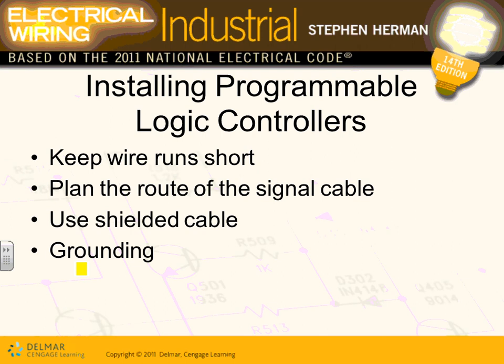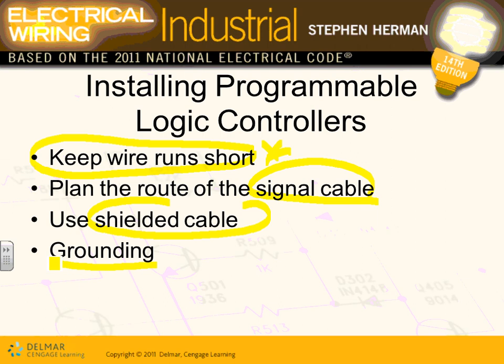Installing programmable logic controllers. So the rest of it, guys, is just installing them. Keep the wire runs short as you put in your conductors. I'm sure Scott told you guys, you don't want to put more wires in the input-output circuit than you need to, because of capacitance and so on. Lay out the signal cables, use shielded cable because of interference, and ground the chassis of the system. So all these are methods. Isolate the circuits from the power circuits. You don't put them in the same conduits because of induced voltage on them.